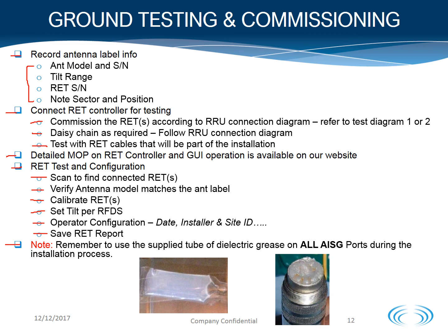Very important note to remember during the installation. Do not forget to use the supplied tube of dielectric grease on the AISG connectors. The dielectric grease is used to prevent water ingress and to prevent corrosion and oxidization on the connection.